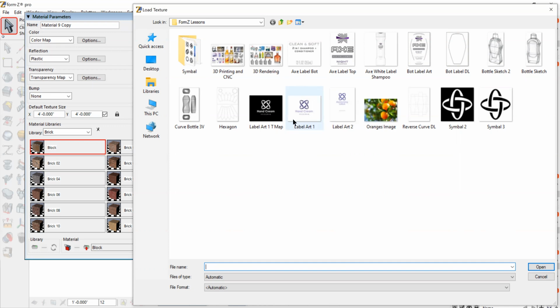But I have this large field around this. I'm guessing that I wanted quite a large area for when I made that as a texture map and I put it onto that label area. So here, I'm just going to use that same piece of art as the color map. And I've also created this other piece of art here. It's a black background. It's the exact same piece of art. It's just reversed, and all the copy areas are dropped out with no color. So the combination of these two things, the transparency map and the art, allows us to create this decal.